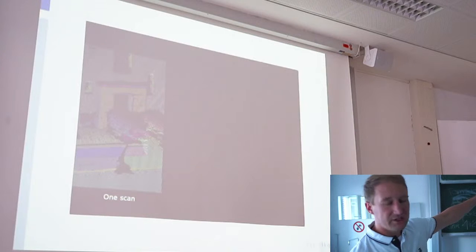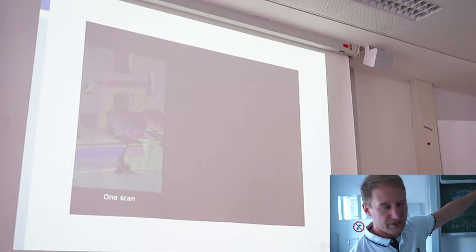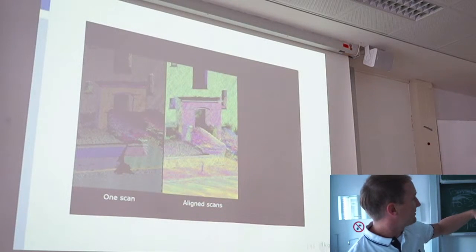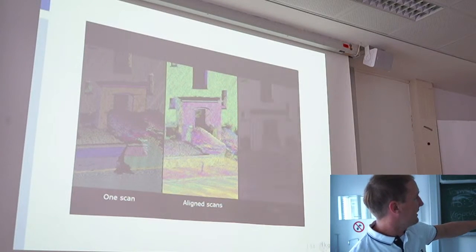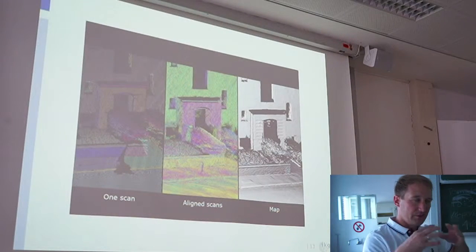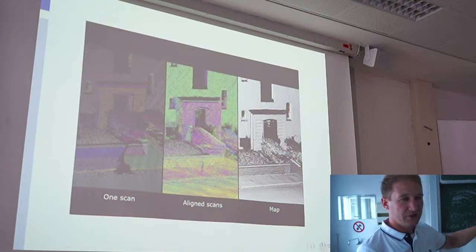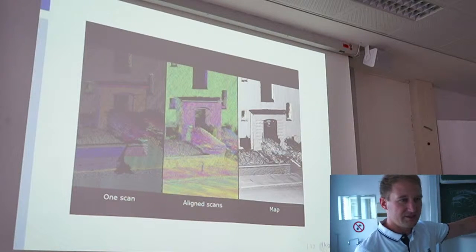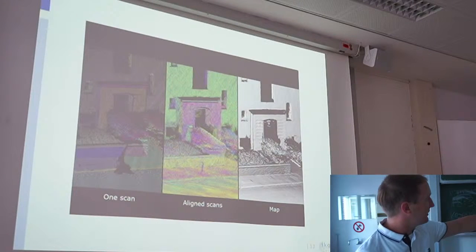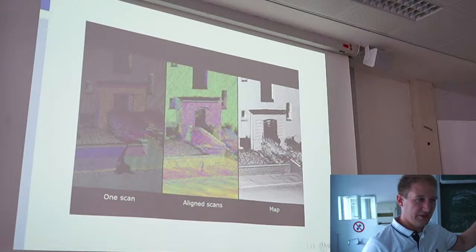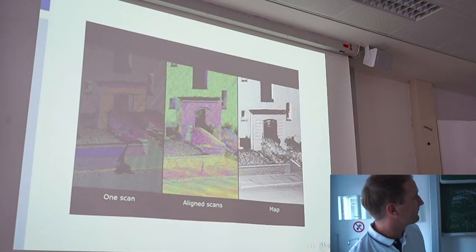So this is one point cloud, right? You can see this facade with the entrance of the building, this small wall at the top end of the street. Maybe we go there several times. You see the different point clouds, different colors here. And afterwards, after this alignment of these point clouds, so we move everything onto each other, then you can have a very, very detailed point cloud. So this is still points, but there are so many points that you just see those surfaces here. And you can nicely see those plates on the pedestrian walks and the different heights. So this is just millimeters, but you can directly see it in these point clouds. So it's very detailed here.